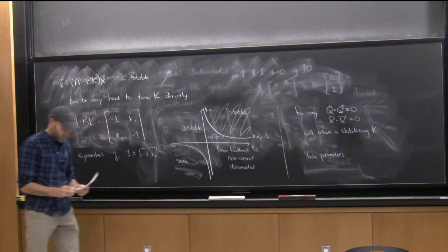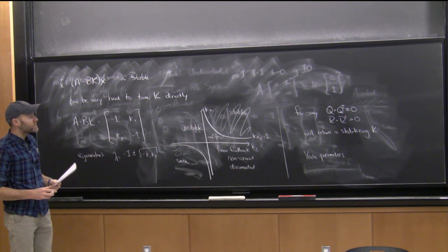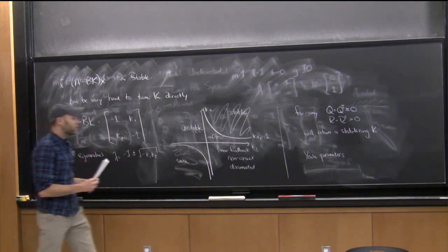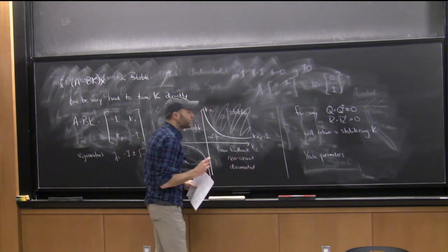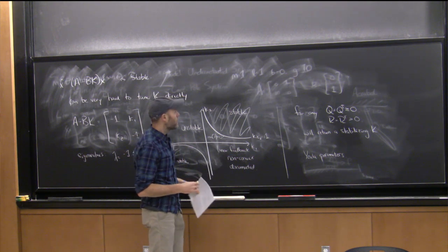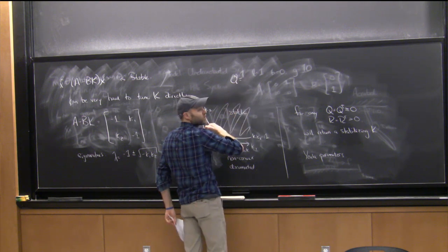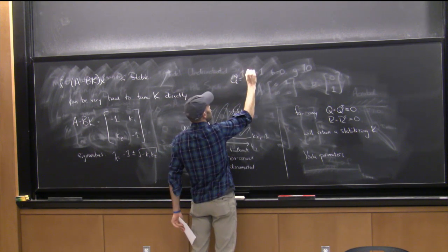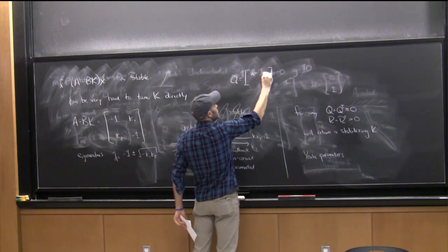It does magical things for you. For instance, how should you pick Q and R? Even for the Pendulum, right? There are some standard recipes for picking Q and R. For the Pendulum, I tend to pick, or you'll see even in the Cart-Poles and Acrobots, you'll see that I will often do something like this.